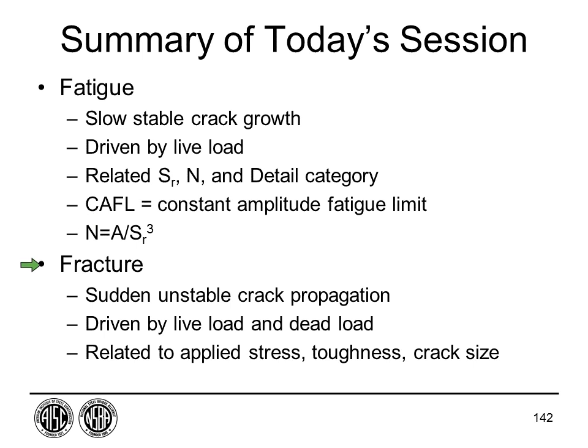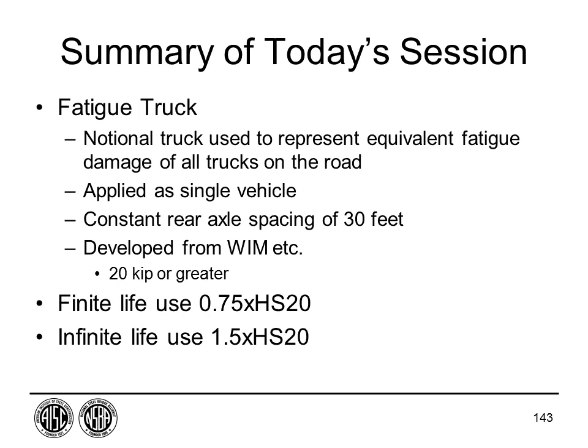Fracture, on the other hand, is fast and unstable. And so it is driven by live load and dead load, as well as the material, the applied stress, and the cracks that could be present. And even if the load goes away, we could still have a fracture if the temperature drops because of its influence on the material. Remember, we talked about the load side, the fatigue truck as well.